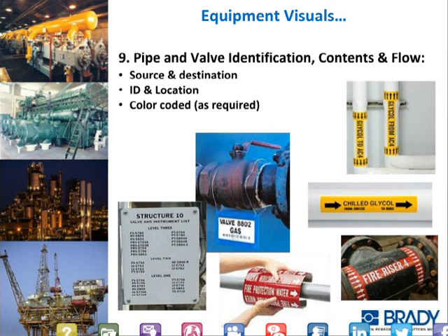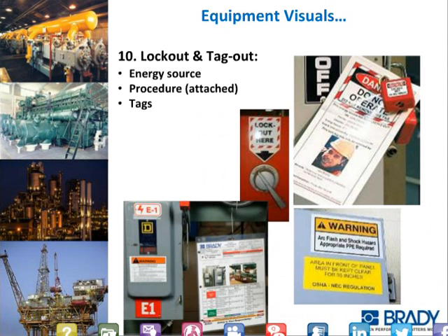Lockout and tagout, very, very common thing. Quite often it's overlooked, and that's where accidents happen. Labeling not only the lockout tagout points, but you notice down in the lower left of the picture is a lockout tagout procedure, a visual procedure. It's a Brady format. It's got the pictures, it's got the step-by-step procedures, it's got the lockout points, and it's got the sequence. And it's also got the information on lock, tag, and try to prove out that these systems work.